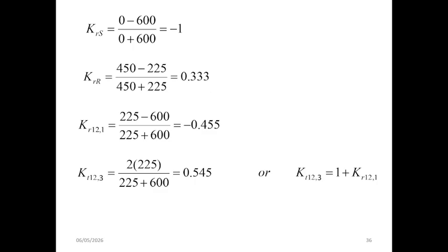So this shows that part of the wave is reflected while the rest is transmitted. Due to moderate impedance mismatch between the 450 ohm and 225 ohm, the calculation results in a negative reflection coefficient, meaning that the reflected wave undergoes a phase inversion.